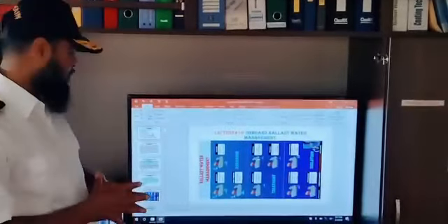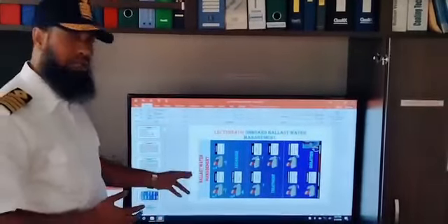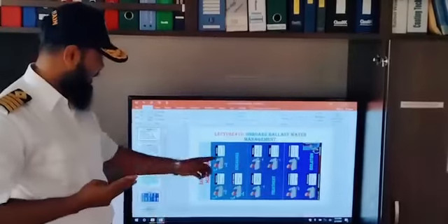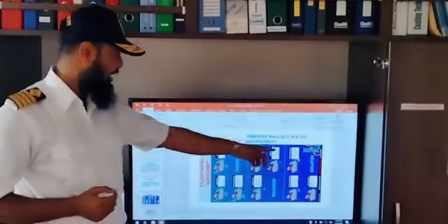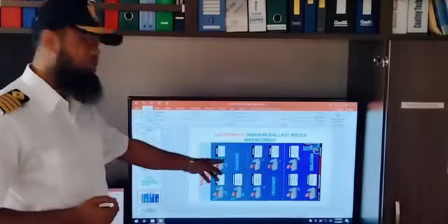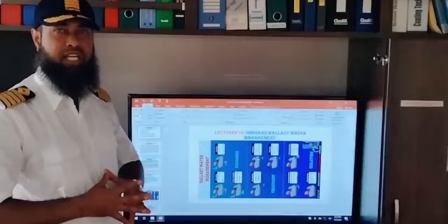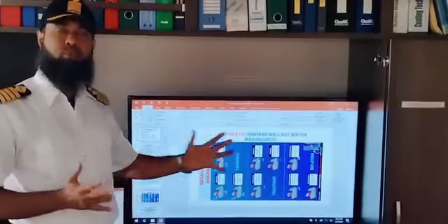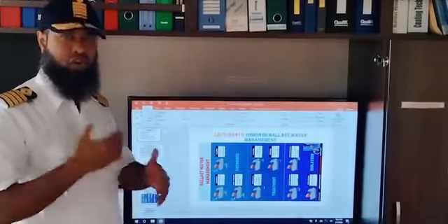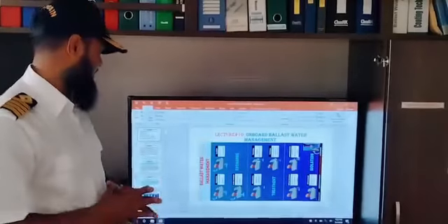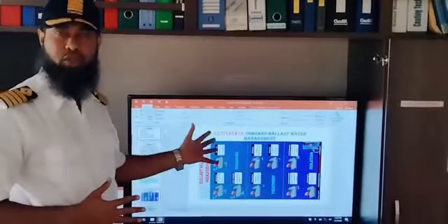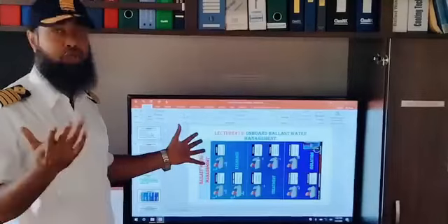Now we can see in this picture that ballast water management has three parts: exchange, treatment and isolation. Exchange at present is basically a contingency plan. Before treatment we used to do exchange for complying with this convention regulation, like the flow through method, empty refill method, dilution method.